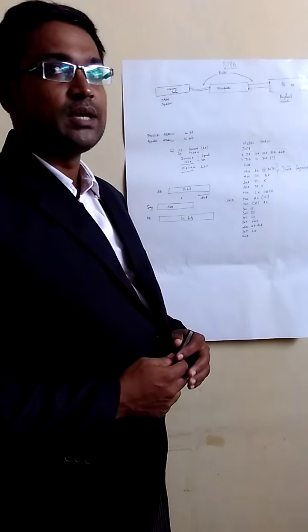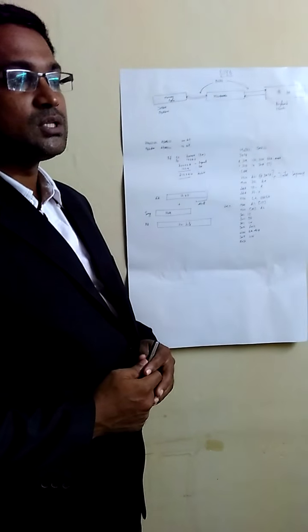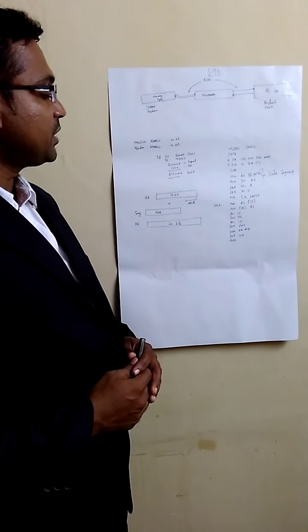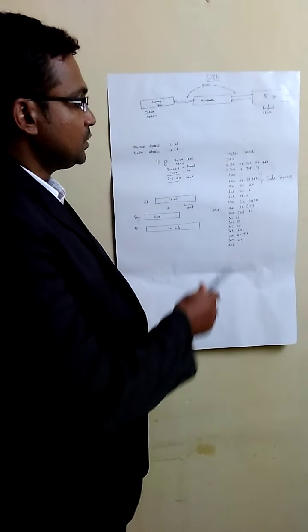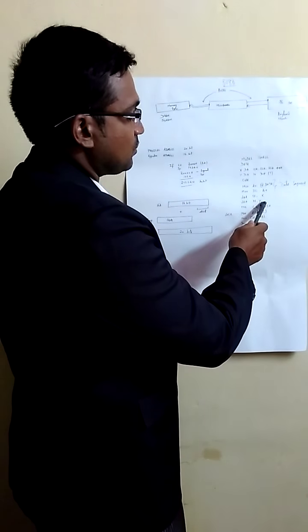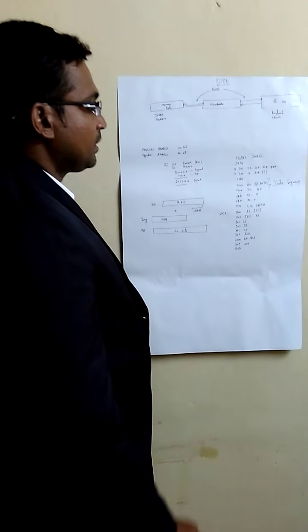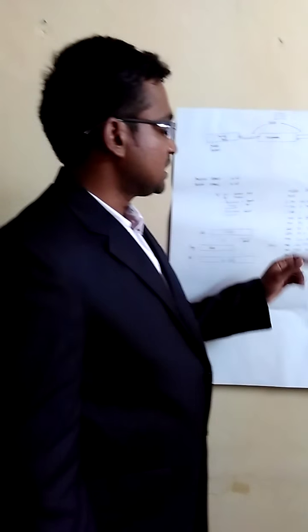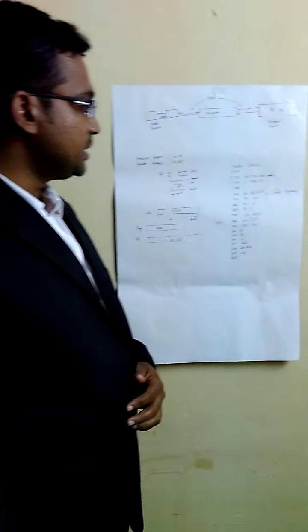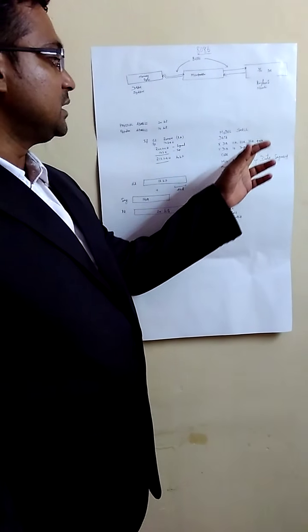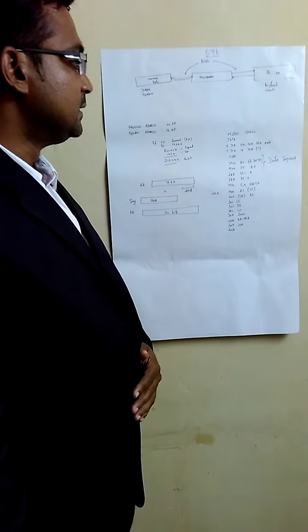We are choosing the index registers. In 8086 we have the source index register, destination index register, and then the stack pointer, instruction pointer. Among those we are using the source index and destination index, and we are getting the addresses of X and Y into SI and DI. After getting the address, we are initializing a counter where CX, which is 16-bit, is used to load the value 004H. However many values there are, that many you have to load here.